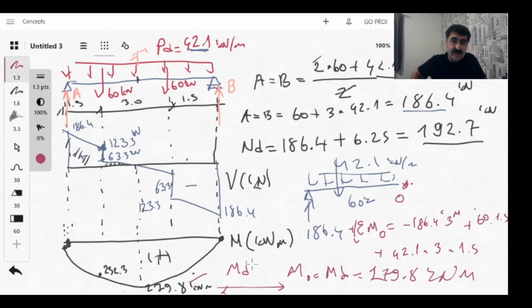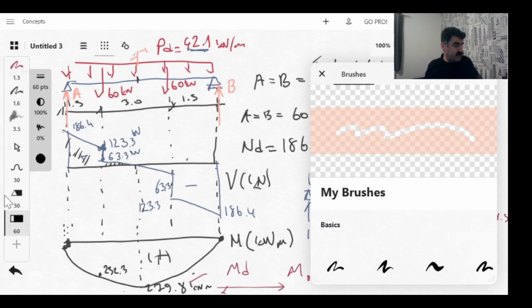Let's check the question. What is section B? Choose the reinforcement bars for the beam necessary to carry the moment found in part A. The moment is 279.8 kN by the way. Following the recommendation of Eurocode 2, any reinforcement bar has to be placed at a distance d0 equal to 50 millimeters. Let me delete what we did now, delete all of them.